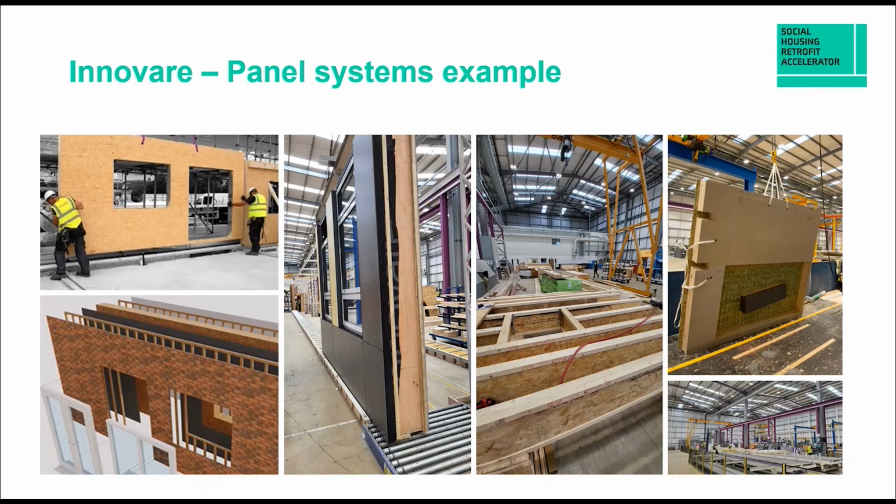Innovare are developing both structural and non-structural panels, so Cat 2 and 5, depending on the archetype. Their panel systems can be clad in brick effect carrier board to match the original design of the building to retain the character of the street. They're working on both smaller format timber SIPs that can be delivered in flat pack form and site assembled, and larger fully constructed facades that can be lifted into place by crane.